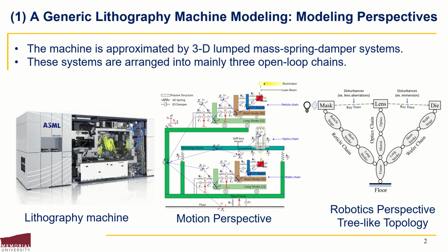Due to the rapid production requirements, various positioning errors take place in the lithography process because of the needed aggressive motion profiles. While studying these errors, the built machine model helps in assessing its performance and the effectiveness of the proposed fine stage in mitigating positioning errors. The motion of the 3 end effectors, namely the mask, the lens element, and the die, must be synchronized during the scanning process. In this study, the synchronization between the 3 end effectors is investigated.